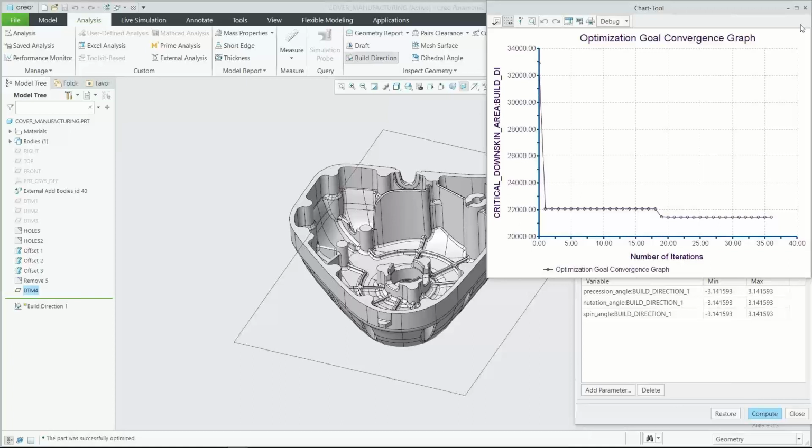Now we're going to go through a little bit of the process of preparing this part and laying it out on the printer tray. Again, this is actually the printer tray that we have out on the shop floor. Right, so we can have that all in Creo, have that linked up to those printers, and then we can send our prints directly from Creo to get printed. So we support direct interfaces with plastic printers through 3D Systems, and also metal printers through Materialise, that type of build processor, which really covers a large majority of the metal 3D printers that you're likely going to be working with.